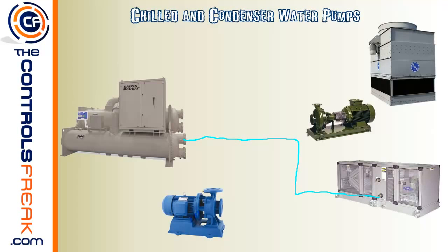Now we want to draw the water coming back out of the coil that's ready to go back to the central plant and get cooled down again. So that'll be this darker color here. And we'll send it this direction. And I'm sorry, pipes don't normally go on a diagonal slant like that, I promise. But it comes into the inlet of the pump. And in case you're not familiar with pumps, if you look at this type of pump here, the inlet is actually going to be this horizontal one here. And there's an impeller in here, so you can imagine it like a boat propeller, but this is an impeller, and it will draw the water into the center portion of it and then spin it around and shoot it out the top here. And this is going to go right back inside to the chiller.